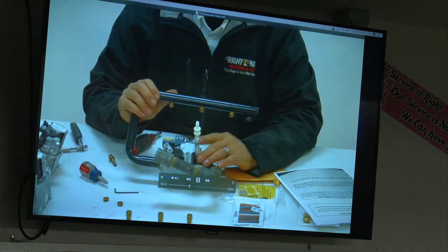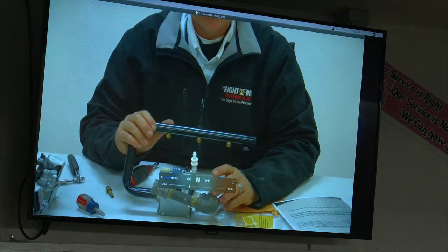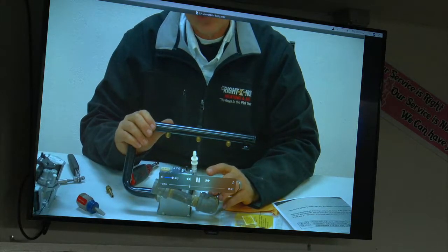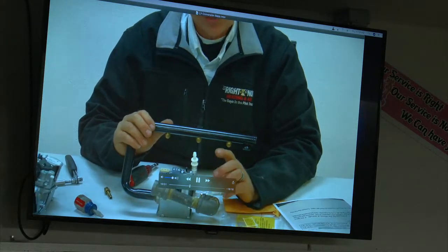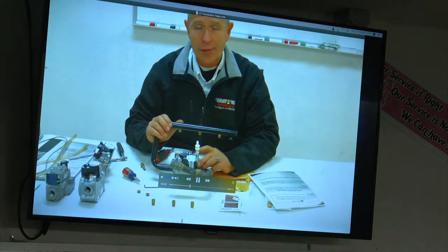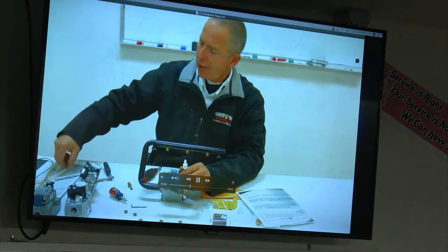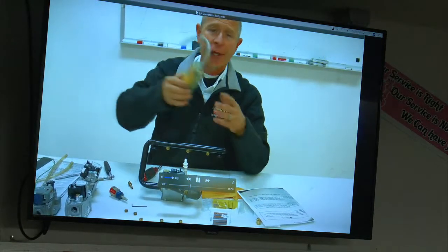When you're opening this up, this being on the meter or the tank side, it will dump gas as soon as you loosen that screw. So you need to turn the safety shutoff valve off prior to setting this up, so that it makes a good connection. And then what you're going to do is take a manometer.